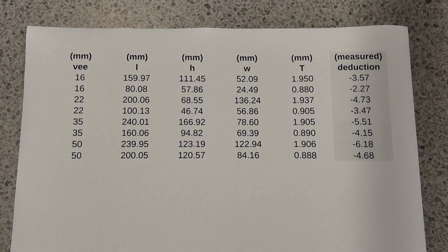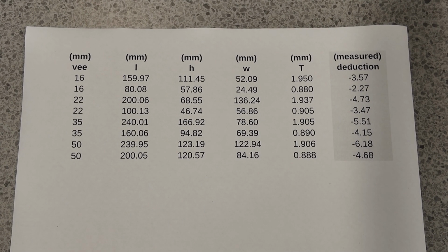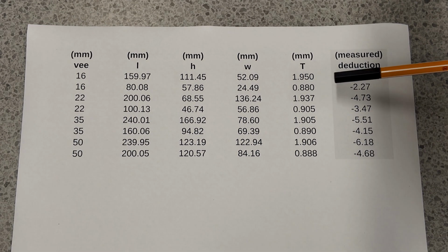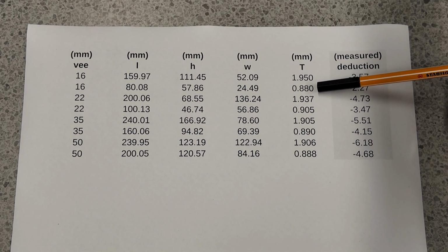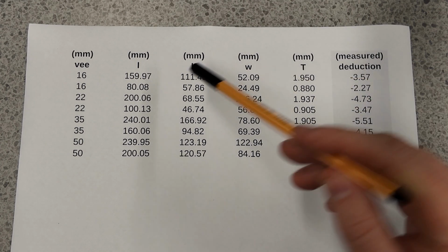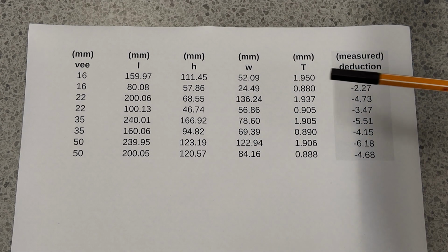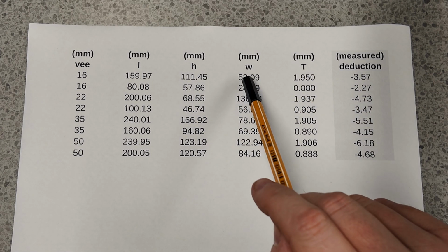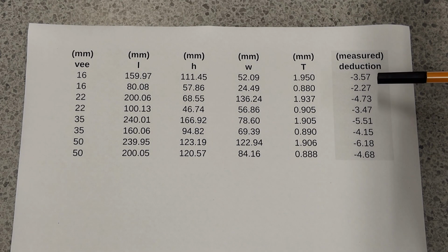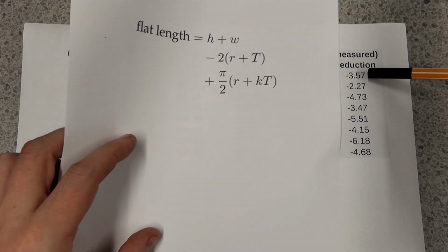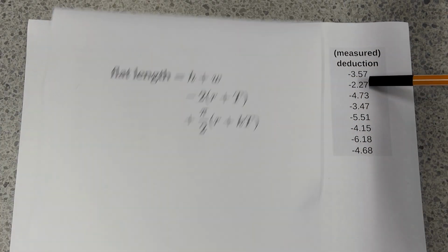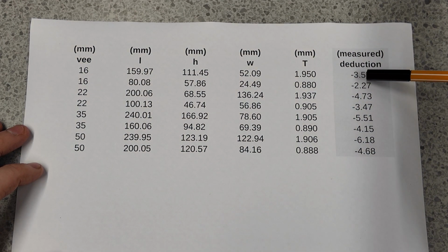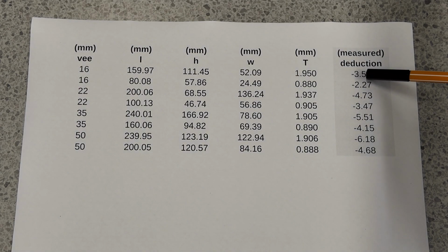So I've typed up the table from the workshop. These are all the measurements I did. So for V width 16, I had material thickness nominal 2 millimeter, nominal 1 millimeter. I measured the length. I then bent it at some arbitrary point. I measured the 2 flanges, and then using that, if you subtract these 2 from L, you can get the bend deduction, which is this bit here. So we can then use that number to try and compute the values of R and K.